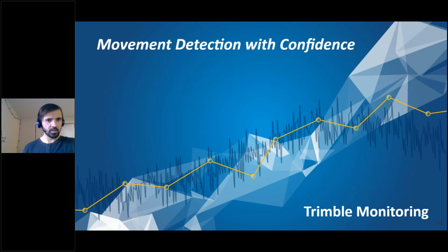All right, question from William. Can we change the initial reading set with latest measurements? Yes, once again, the best way to do that is, for example, I have 4 epochs, which means I have 4 TBC projects. And let's say for epoch 2, I need to change those measurements. Maybe I used the wrong prism. You would open that TBC project, update all those prism types in TBC, and then resynchronize the project, and it would update all of that coordinate information to the monitoring project. So any time you run the report or the charts later on, it'll have the updated values.